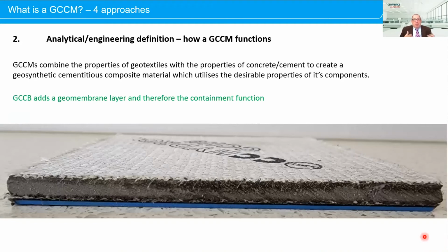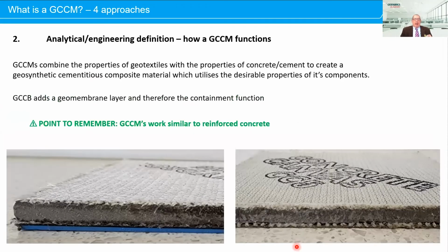And a GCCB is the same, except it also adds a geomembrane layer and therefore a containment function, as you can see here. Okay, an important point to remember is because you have a cementitious component and a textile reinforcement component, GCCMs work similar to reinforced concrete.